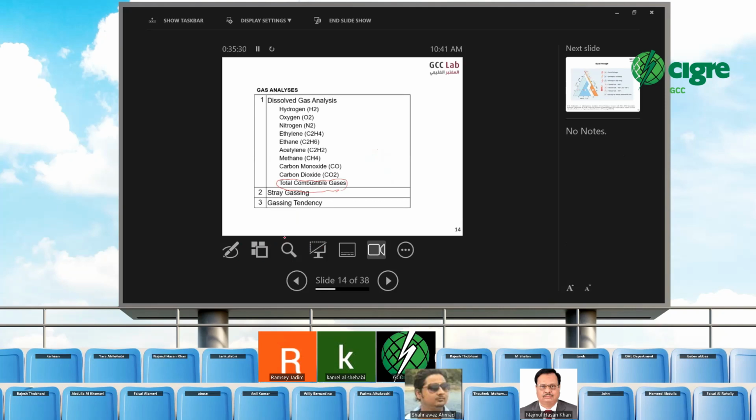And maybe it's not written here, the equilibrium gas pressure is not written here. Equilibrium gas pressure gives me information on the ability of your oil to create gas bubbles based on the gas concentration, and also based on the aromatic content of the oil.